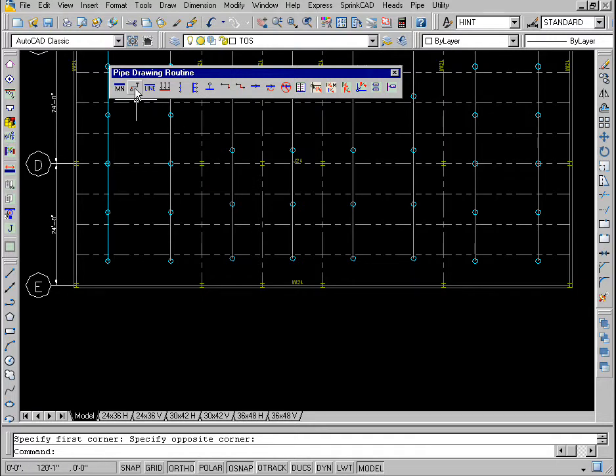Select Auto Draw Main Pipe again. You'll be prompted at the command line, Riser Main Start, Cap Starts Main. You want to start with a cap, so enter C at the command line and press Enter. Enter TRA at the command line to start tracking.